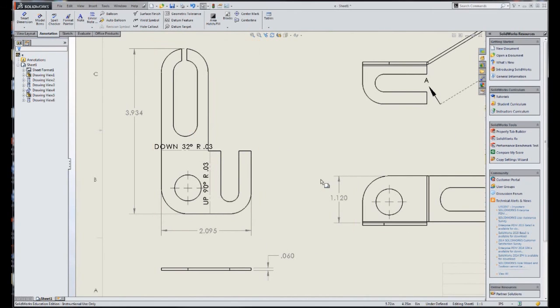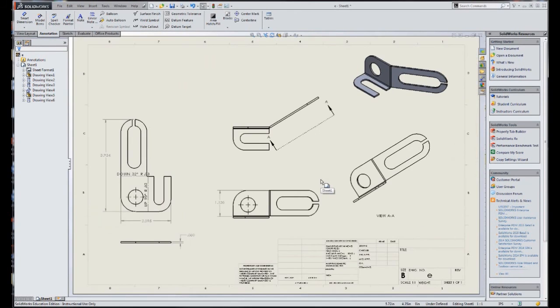The other thing is you can save this whole drawing as a DXF, and then they can take this drawing, and again, these dimensions are very important, that when they get the DXF, especially of the flat pattern that they're going to put into a laser or a water jet machine, they can make sure that these 2 dimensions are the dimensions that you're looking for.